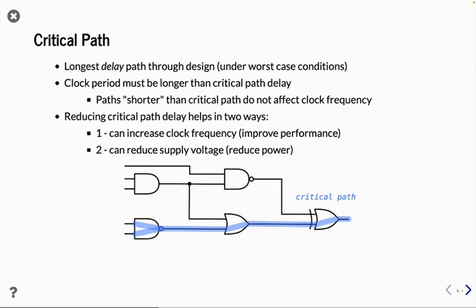But independent of power, how fast you can run is determined by what produces the correct solution, right? And so you actually can't go arbitrarily fast. You can only go as fast as the slowest element, right? And the slowest element is the critical path, which is a straggler that sets how fast you can run things, right? And so however fast your clock is switching, it needs to switch at a rate slower than the critical path delay, right?